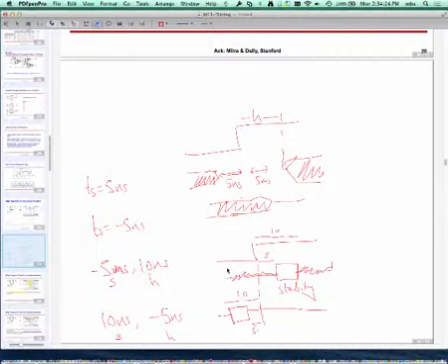So setup, hold time, very important concept. They could be negative because of additional delays inside the circuit path. But the basic concept is they define a period of time near a clock edge in which the data input should not change. If the data input changes, then the flip-flop will misbehave, and as a result, your sequential circuit will misbehave. Any questions before we go?